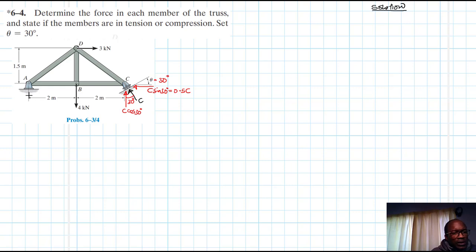Right. So at A, which is a hinge, we have these reaction forces. We have AY, and then we have also AX. Alright, I guess we've drawn all the reaction forces. Let me just also draw the slope. Here we expect the slope, using a triangle to determine our slope. Right angle triangle.